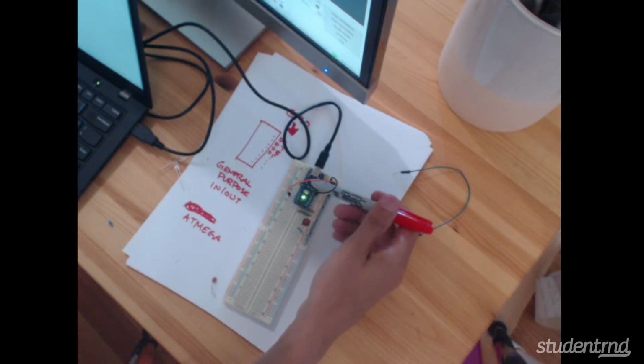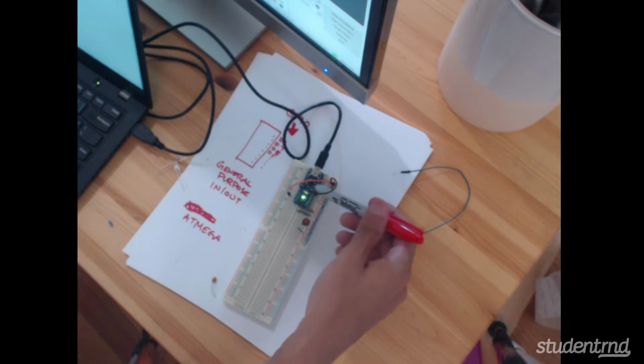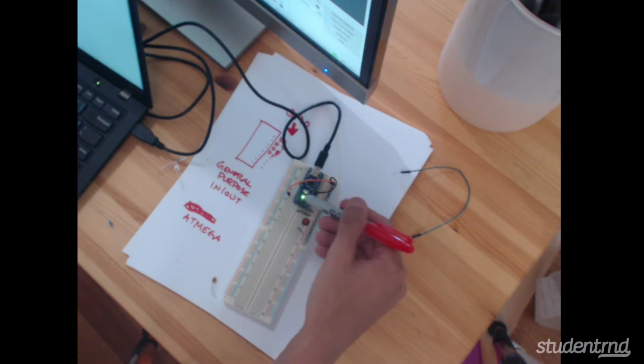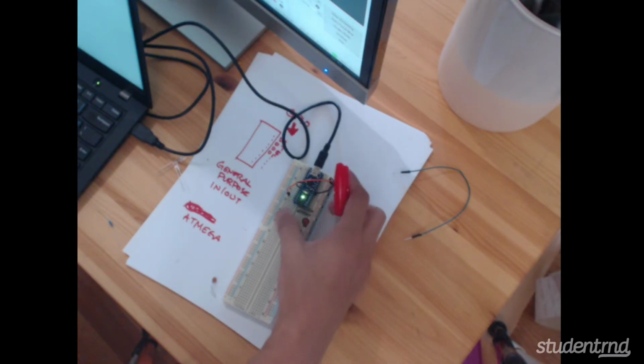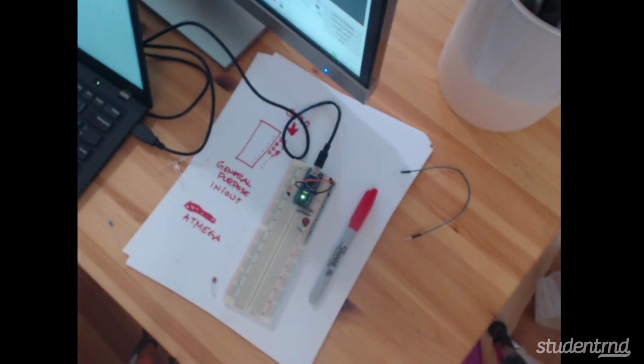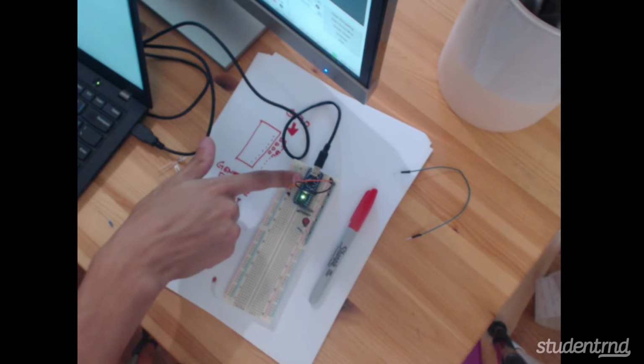So if you look at the Arduino, you can actually figure out exactly what's on it. You've got this ATmega. You've got a crystal, which is literally a crystal that oscillates at a specific frequency because computers need clocks to keep track of time. You got a button. You got 4 LEDs, 4 resistors because you can't just have LEDs, a bunch of pins, and then I think on the underside of this there's a few more chips. There's some capacitors, some resistors, and probably a thing called an FTDI chip. But fundamentally, this ATmega is what we're actually going to be programming, and all the rest of the Arduino, all you're paying like $20 for or whatever it is, is fundamentally just for them putting it in a really nice package for you. So just to be clear, there's nothing fancy about an Arduino.